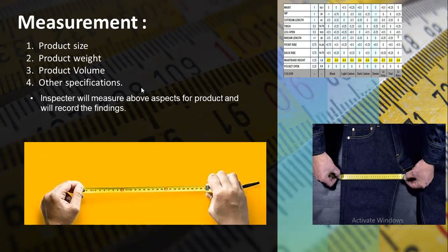If it is within tolerance, we keep it as it is. If it is a minor deviation based on their requirement, we highlight it in yellow. If it is a major deviation, we highlight it in red with supporting images. We have to provide supporting images for every point of measurement for major deviation.